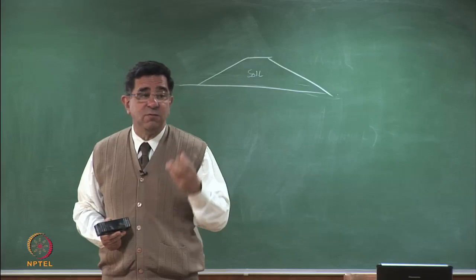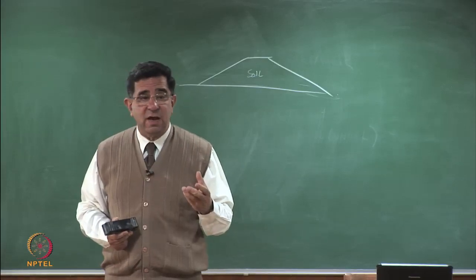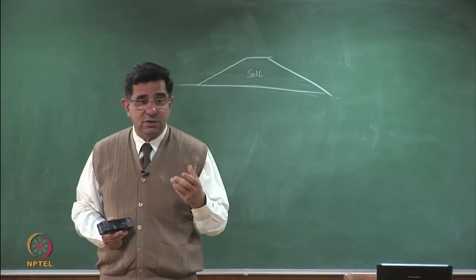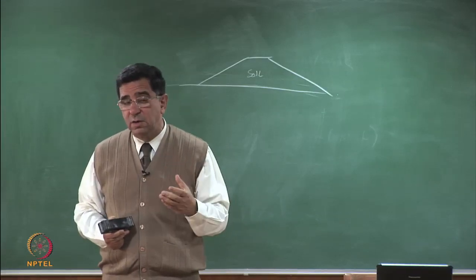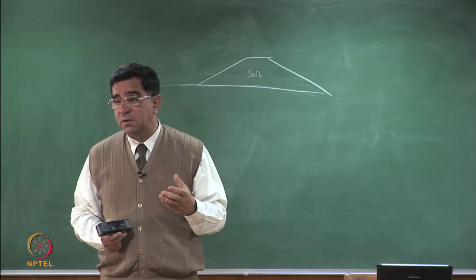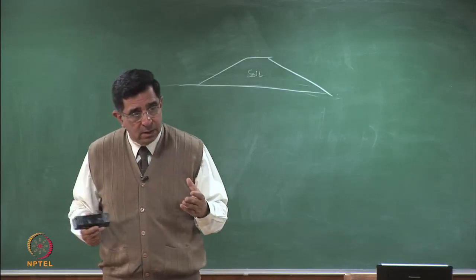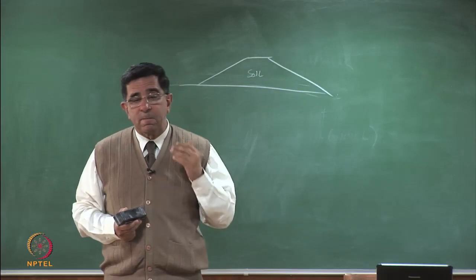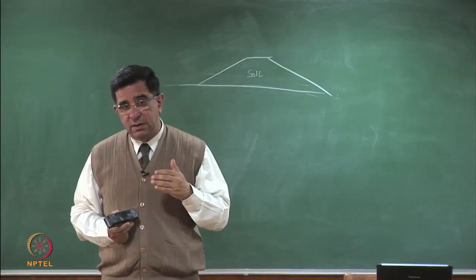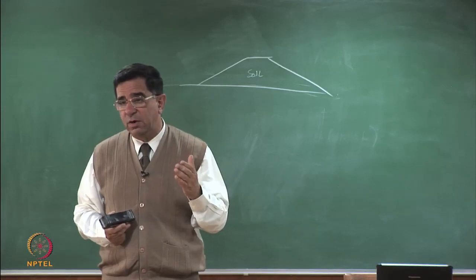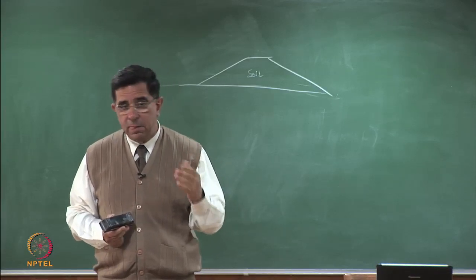If it is gravel, you will have to use a large size triaxial equipment, or you could use the direct shear test. In the direct shear test also, the conventional 6 centimeters by 6 centimeters direct shear box cannot be used for gravel. You will need a bigger direct shear box. So, I can do the tests in the laboratory. Triaxial tests give better and more accurate values than direct shear tests.